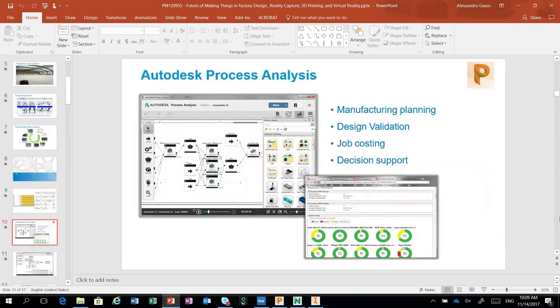While with process analysis, that is one of the factory tools, basically we can create a process, we can simulate a process with data, animate it, so we can simulate if we have hiccups, if we need bigger buffers, what happens if a machine fails for a certain amount of time, and we can check everything before even drawing a line, and of course before setting up anything physically, and then realizing that there is a problem, there are things that we have overlooked, and so we need to do some costly change.